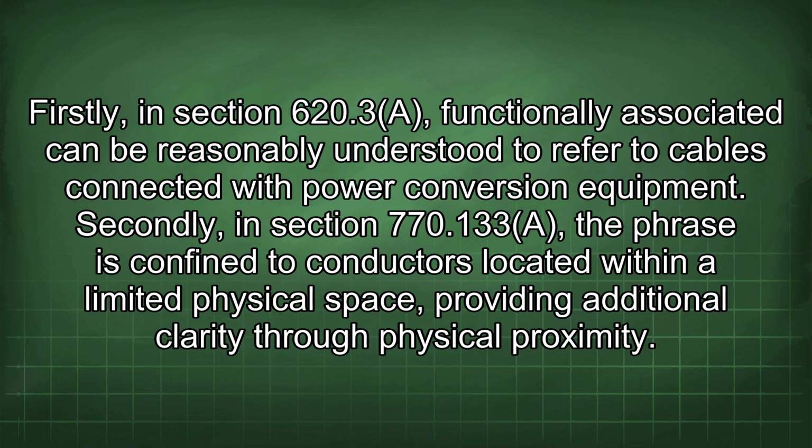Firstly, in section 620.3(A), "functionally associated" can be reasonably understood to refer to cables connected with power conversion equipment. Secondly, in section 770.133(A), the phrase is confined to conductors located within a limited physical space, providing additional clarity through physical proximity.